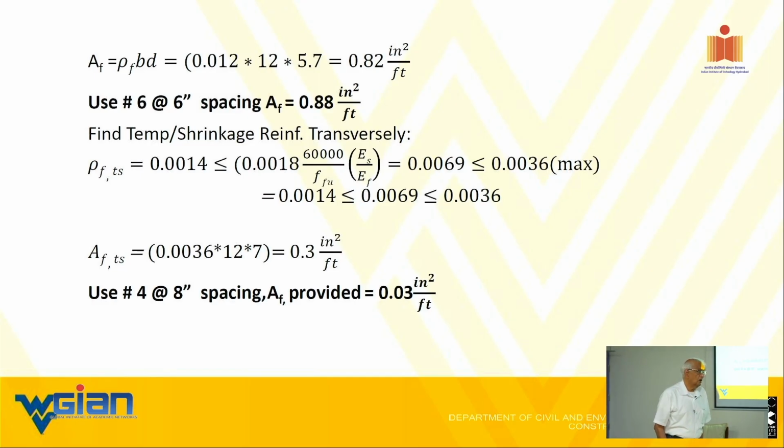So much so that creep load, primarily under the self-weight, resulted in slow but steady increase in crack growth. By the time we realized it, it was too late. It looks good on the first day or 2 days. Once you go beyond that, you'll begin to see the cracking.